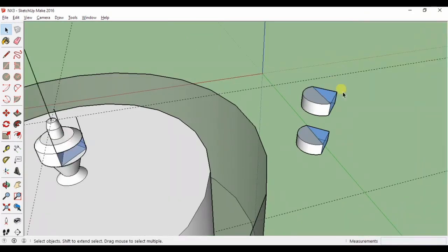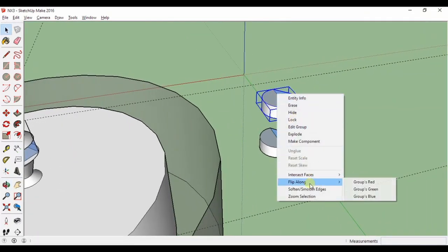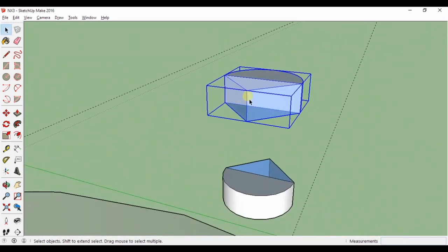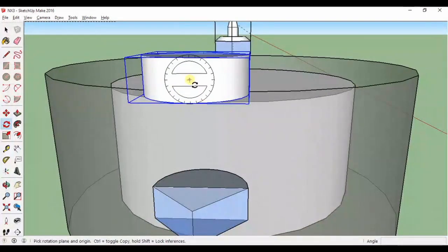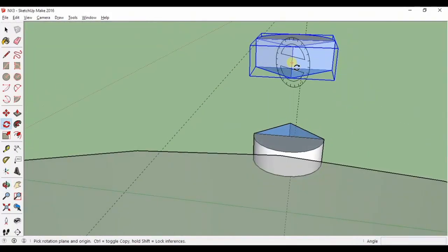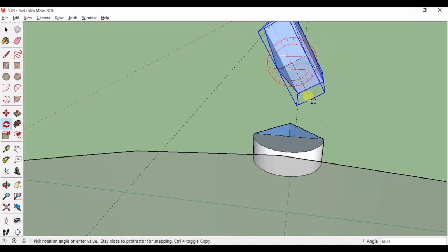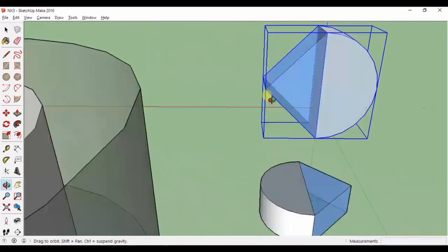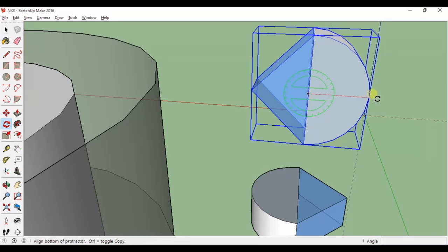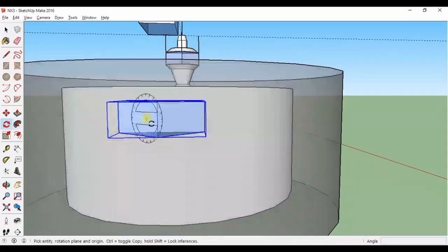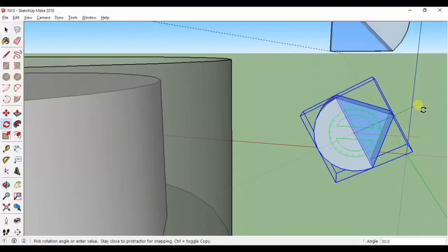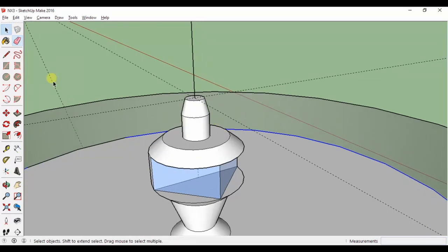I need to angle the mirrors correctly, so let's flip the top mirror, which is the moving mirror, along the red axis. Now, here's where a SketchUp tip comes in handy. I want to now rotate the mirror 90 degrees with the Rotate tool, but to do so accurately would be rather difficult, since there's no flat surface for me to work from. So instead, I can use the arrow keys to align it with the red axis, specifically the right arrow key, and now I can align it on the piece and it will always stay perpendicular to the red axis. Two more rotations and it's oriented. A similar process can be applied to orient the fixed mirror and also the rotating mirror.